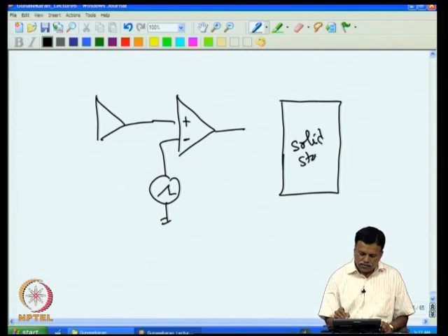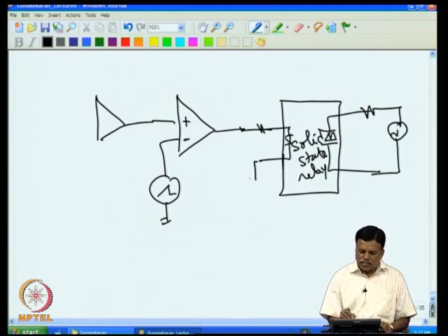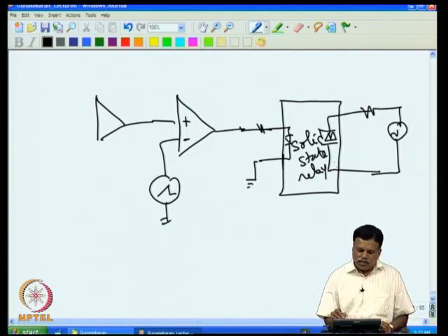It is available, which contains the thyristor and all that stuff to go with that. Then in the other side you have this thyristor connected inside and all that firing circuit. All the firing circuit also built in. All that you need to do is connect this. So life is a little easier when you do not struggle, and you got isolation and firing circuit, everything. Whenever this is high, this will be on, and whenever this is 0, it is off.